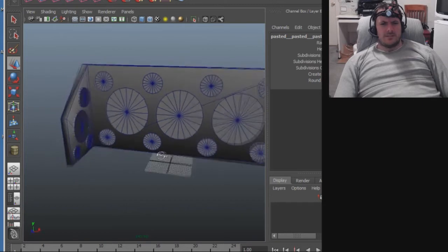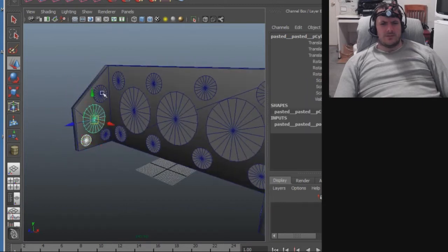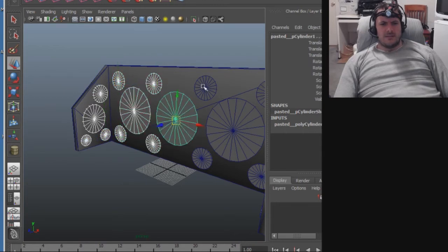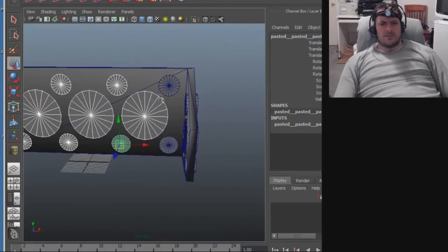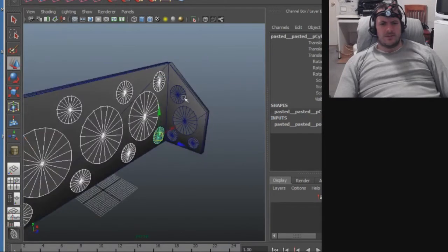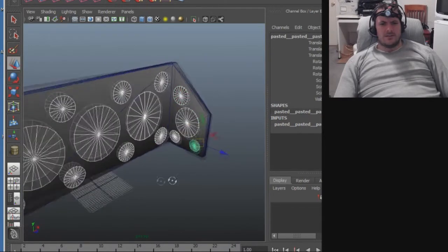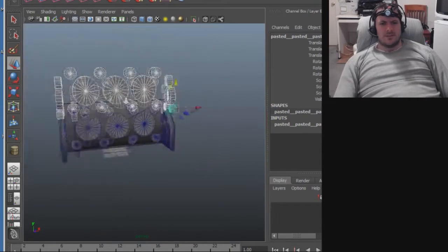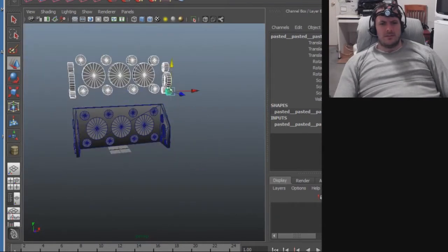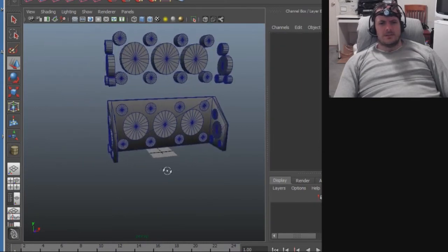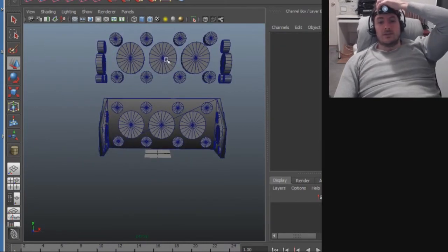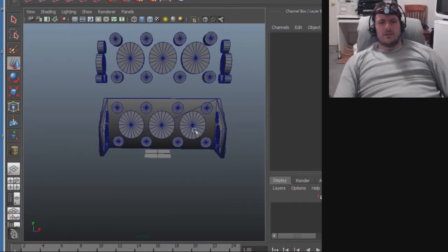Okay, I just copy pasted it with Control C, Control V. I'm selecting them all, and I'm going to move them out of the way, upward, just to store them, because we're going to be deleting these shapes, leaving just the holes. I want to store them in case we have time to 3D print these as separate prints, and then use these 3D printed plugs to fill in all the holes left in the model.